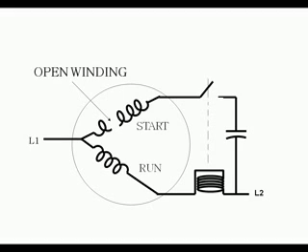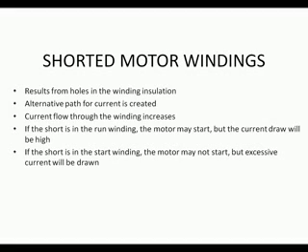If the motor's hot, let it cool before you take these resistance readings. There might be an internal thermal overload. If any of these readings do not work, you're not going to fix the motor in the field. Just replace it. This is an example of an open winding.